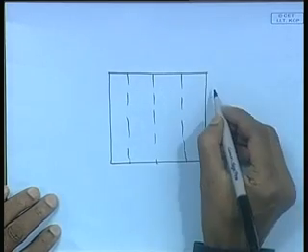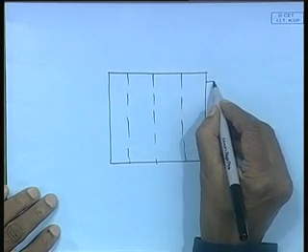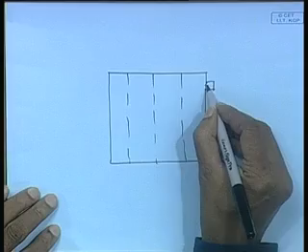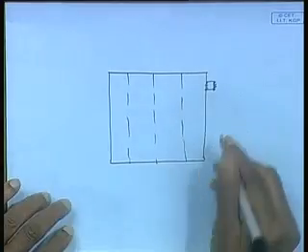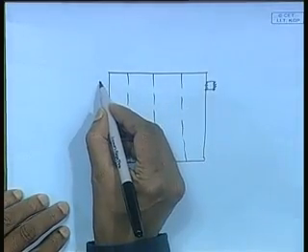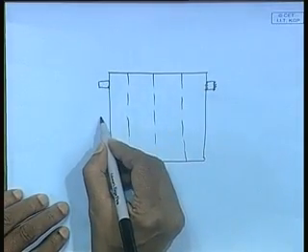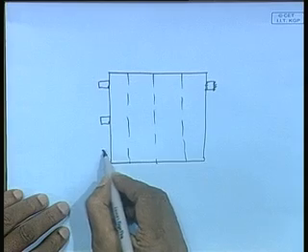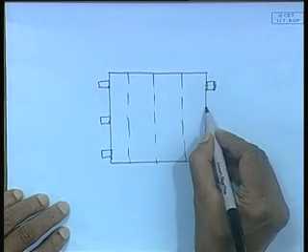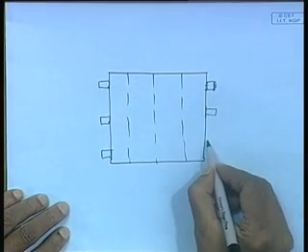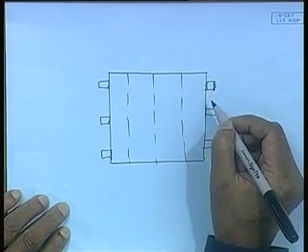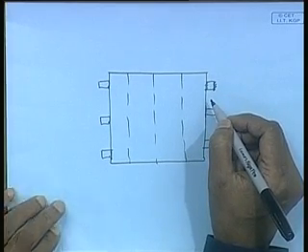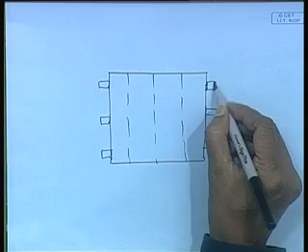So, I put the plate, and then at locations I weld certain lugs with the skid. Again, it is a flat horizontal skid over which it is placed, right. So, such lugs are welded. What I do just before welding, these are small lugs: before welding, I heat up the lugs, they are hot, and then I weld it.